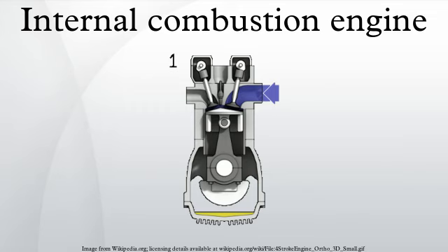This heats and expands the air, and this extra energy is tapped by the turbine, which in turn powers the compressor, closing the cycle and powering the shaft. Gas turbine cycle engines employ a continuous combustion system where compression, combustion, and expansion occur simultaneously at different places in the engine, giving continuous power. Notably, the combustion takes place at constant pressure, rather than with the Otto cycle, constant volume.